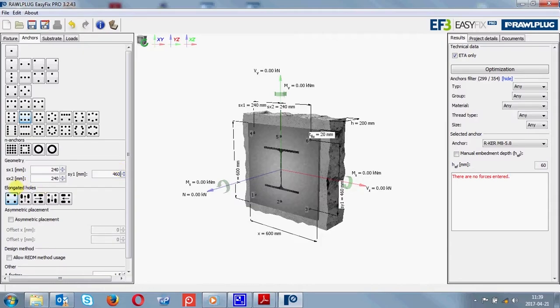Another available option is to introduce elongated or bean-shaped holes along the chosen baseplate edges. This will prevent the given row of anchors from transferring shearing forces towards the edge. There are no edges in our case, so let's leave all anchors marked. You can also distribute anchors asymmetrically against the baseplate.